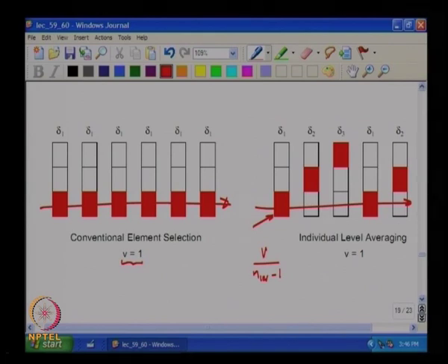It is not very apparent that mismatch is noise shaped. One thing you can say is that if you think of the error sequence, the accumulated error, sigma error, goes to 0 after every 3 cycles in this example.